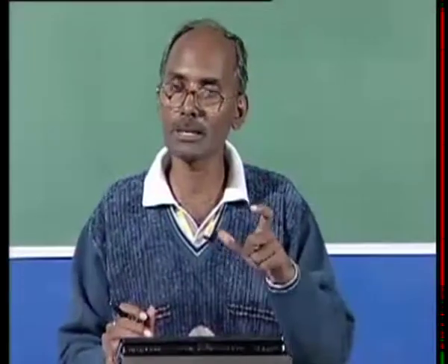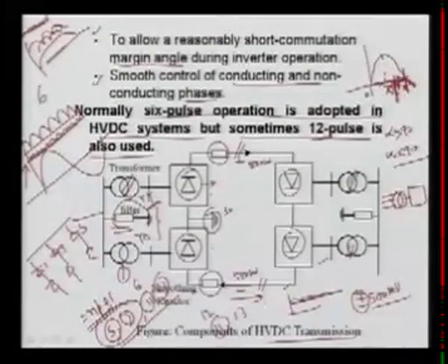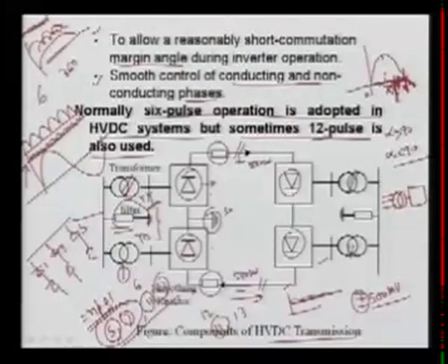Automatically the two 6-pulse converters are connected, because we have the inherent property of this 3-phase connection, a 30 degree lead. So here in 360, earlier it was 60, 60, now we have shifted 30 degrees and 60, 60. So in 360 we have 12-pulse operation, and the same 3-phase transformer is very good for using the 12 pulse, and normally we go for the 12-pulse operation rather than using 6-pulse bridge converters. So this converter operation, its analysis and its performance are very, very important, and if we have time, we will discuss that as well.